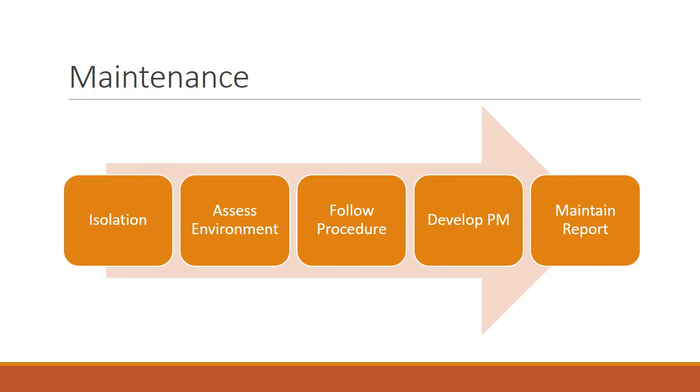However, determining when switchgear should be replaced or properly maintained is difficult with old equipment, because often parts are quite expensive or scarce for these old equipments, and retrofit may not actually be available. So in this case, you might need to do a redesign to accommodate a new switchgear for replacement.